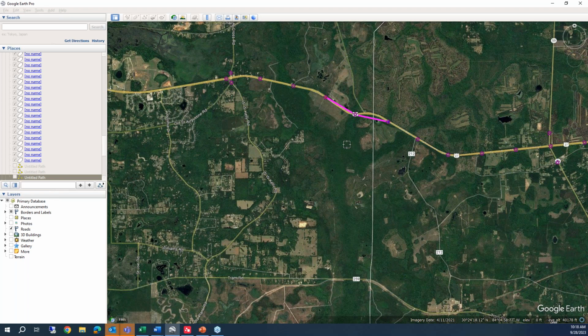Just a rule of thumb for your independent baselines: the number of stations being observed, minus 1, equals your total independent vectors. In this case, we have 3 rovers and 4 FPRN stations for a total of 7. So 7 minus 1 is 6.